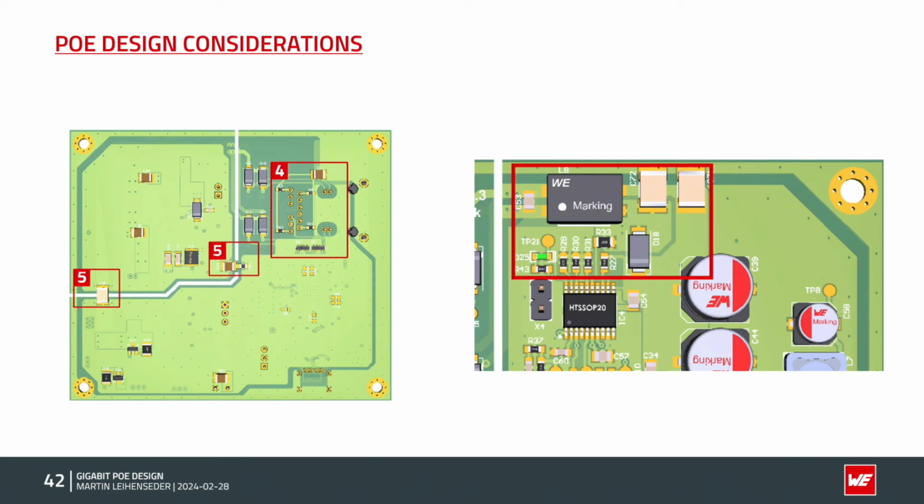You see, for example, the common mode choke that we did and the capacitors. This array is after the diode bridge. So after the transformer, there is a diode bridge, a rectifier diode. And between the rectifier diode and the DC-DC converter, we have some filters. We need big filters because the current is high.